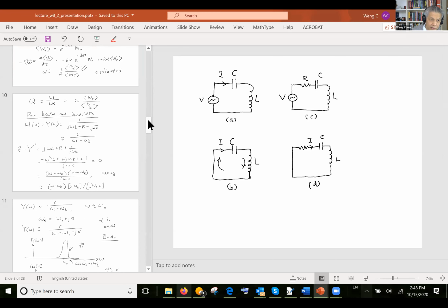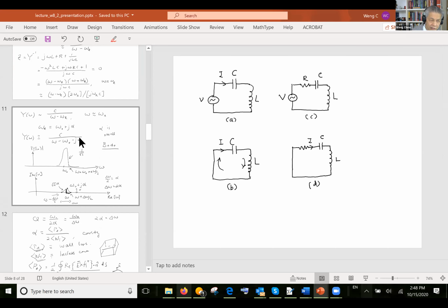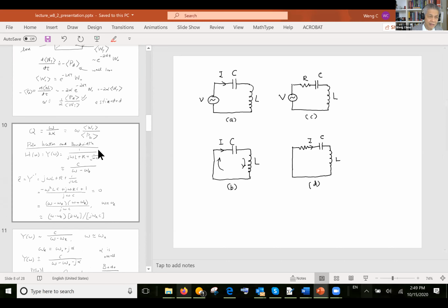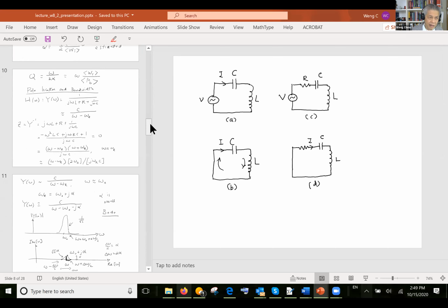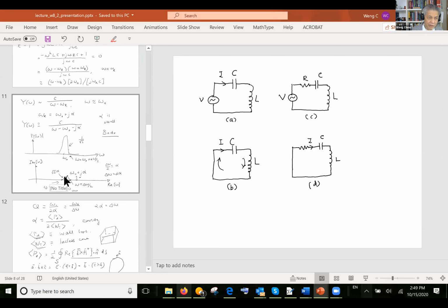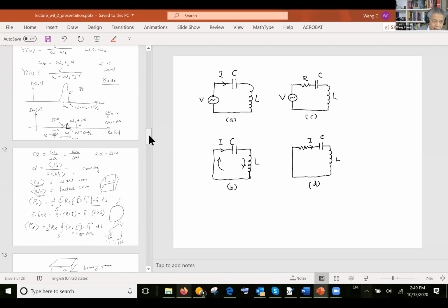Once you have found this decay factor, you can show that it is related to the bandwidth of the system. I used a very simple RLC tank circuit to show that the bandwidth and the pole location are very much related, as long as you can approximate the transfer function of the system by a single pole.